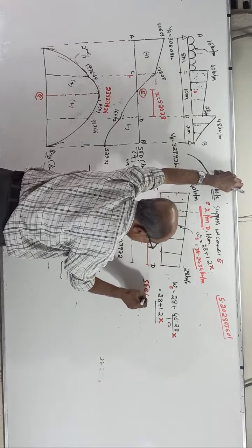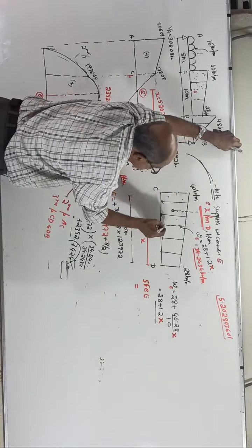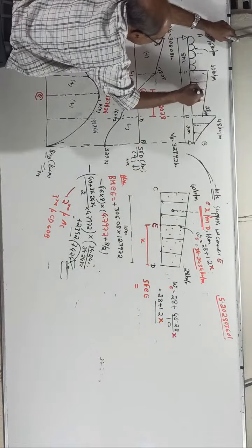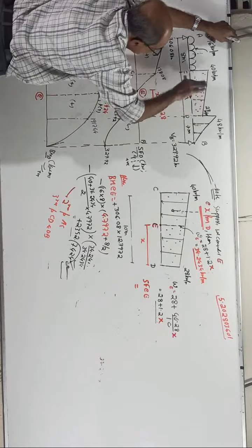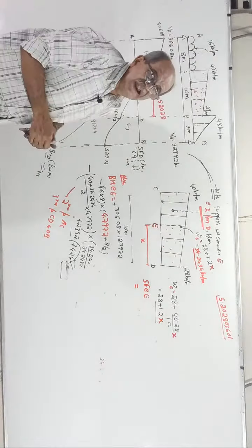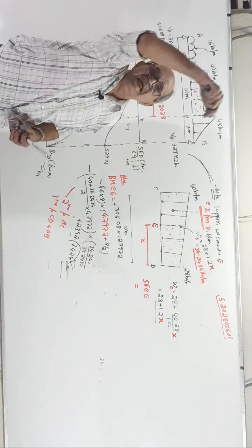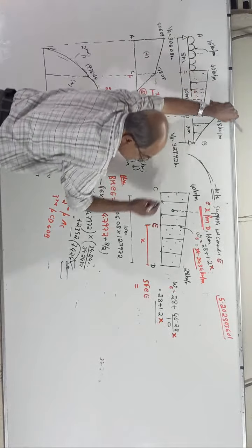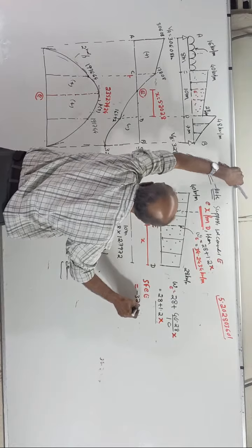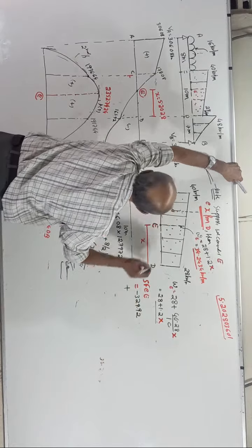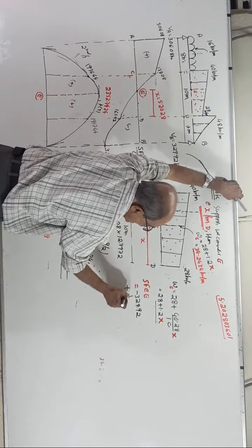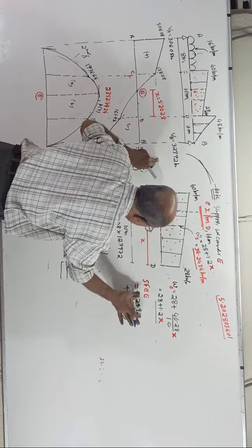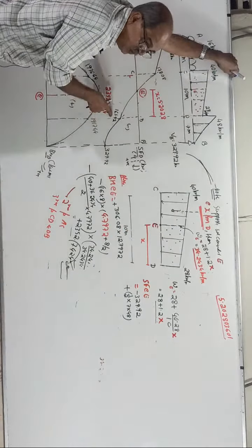Now shear force at E equal to, you want shear force here, look this side. Here also, not that side. See, at E here, look this side. Okay, start. When you look right side sign is left up positive, right down positive. Sorry, I should not have told it. Right down is positive. So, minus 329.92 plus this triangle load half into 7 into 48, actually not required. That much answer is minus 161.92.